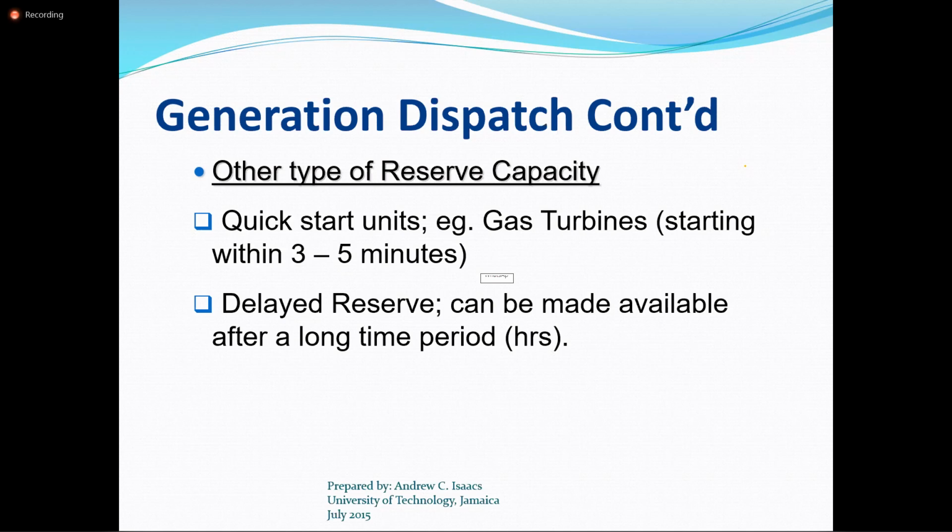If the fault was what we refer to as an incipient fault, meaning that it was just a momentary fault, in reconnecting the system, if the fault had been cleared, then the system would just continue operating as if nothing happened. So the automation I mentioned was really speaking to that, not the generation side of things.